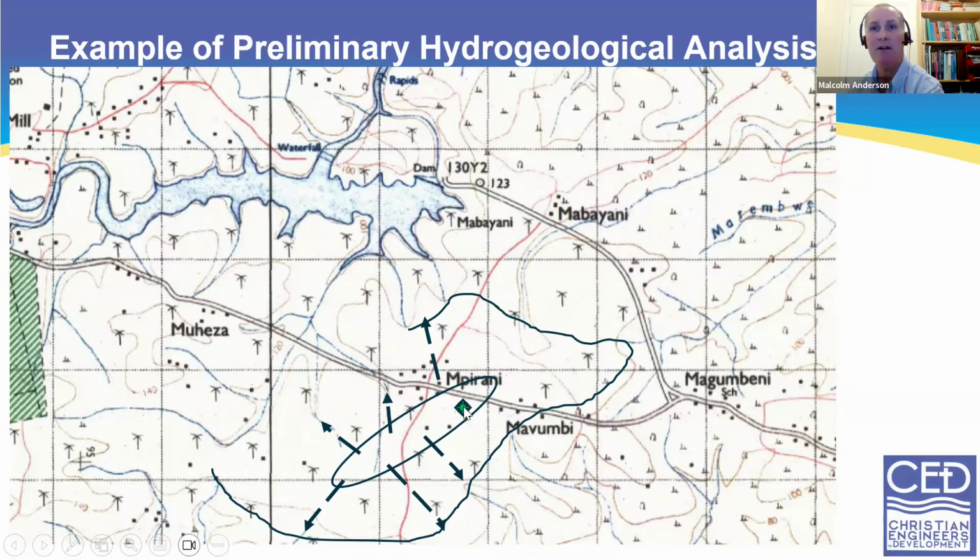And then in my site itself, one of the possibilities is that the flow is towards the northeast. But compared to the nearest discharge location, which is the spring here, to the site, that's the shortest route. So that's the one that I'm expecting the groundwater flow direction to be, just because water takes the shortest route.